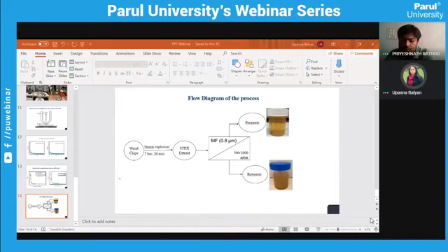If you have collected 10 liters of steam explosion extract, you should have a 10-liter feed tank, and then you will foul the membrane for 8 hours or 10 hours, up to your requirement. You run the setup and let the membrane be fouled. Then you are ready to examine the fouling layer. Now you will run the FDG probe.